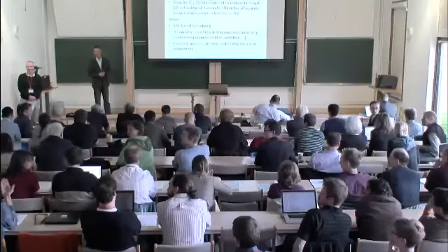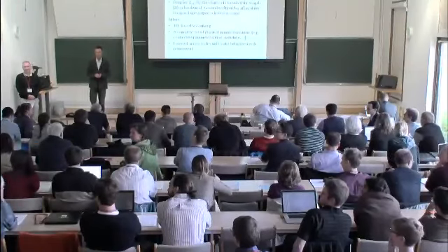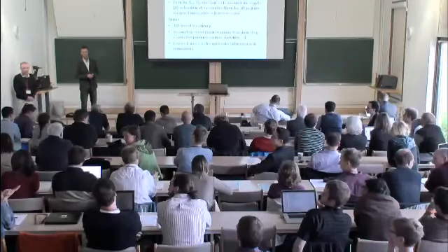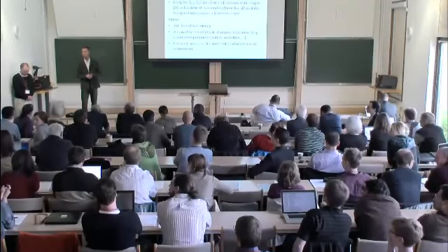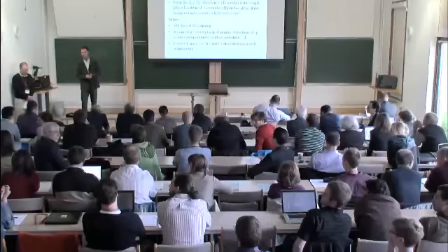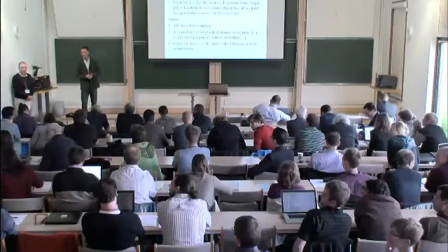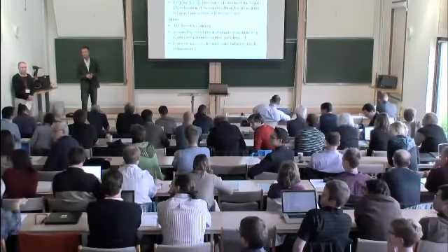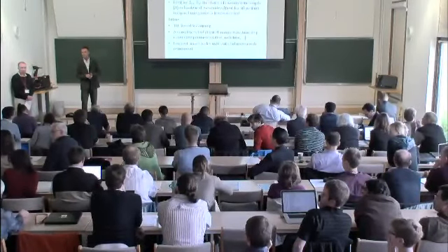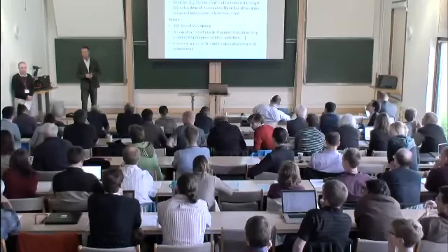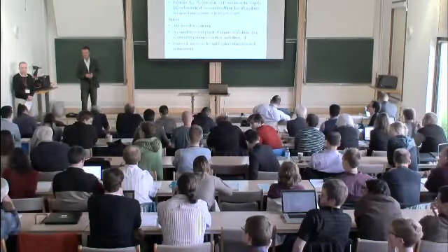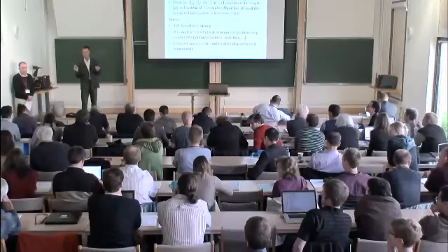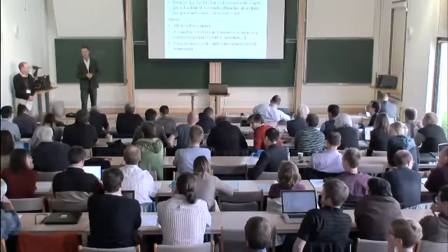Yeah, so in your Km analysis for the shear jet, you had rather different results, I think, for the different strategies for choosing delta. Have you thought about trying to use a very high-resolution simulation that would actually capture much more of the turbulence and try to see which strategy was most faithful to producing the correct subgrid scale behavior? Kind of like an LES approach. Something like that, yeah. That's the idea.